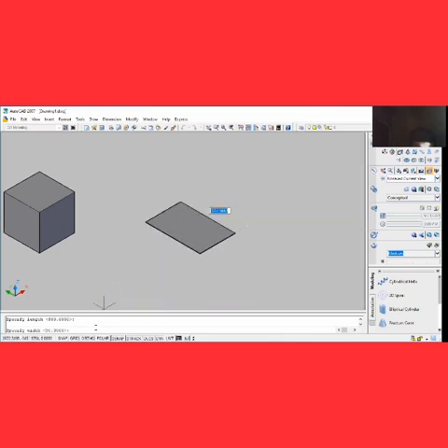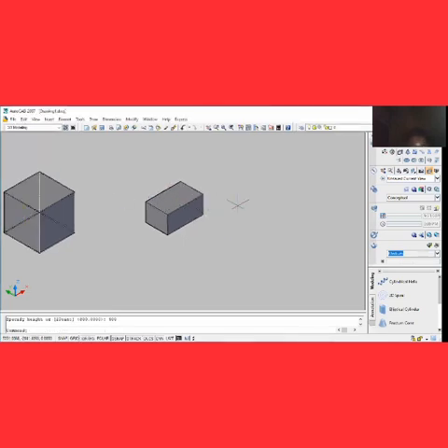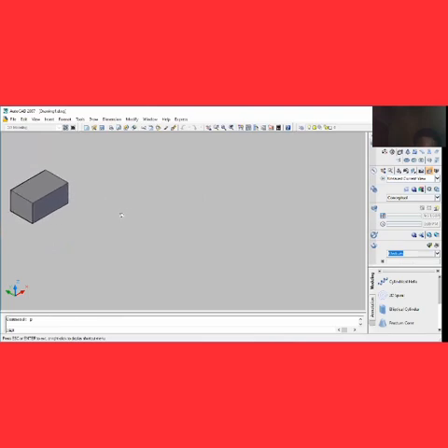And then let's choose a width of 500, enter. And then let's choose a height of 400, and then enter. And this is your box. So you see this is a cube, but this one is in cuboid form. So let's pan and then enter.